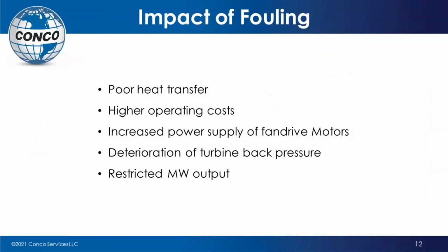So now on most of these larger fans, you have some sort of variable frequency drive that will increase or decrease the speed of the unit based upon pressure. And that pressure, as it begins to increase, causes that fan drive to increase the speed of the motor itself. And so the fans begin to turn a little faster. What happens now is that you're trying to force that air up through the system itself, and you're getting a higher pressure, and you're not getting much more results.